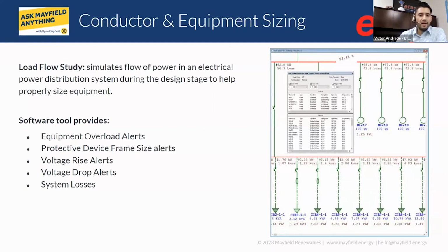Load flow analysis, or a load flow study, simulates the power flow of an electrical system during the design stage. And this is so important because it helps us size equipment such as transformers, cables, inverters, and very importantly, conductors.